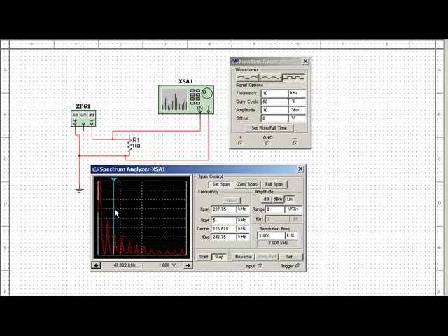And then over a little further, this should be 50, about, yeah, there we are, about 50 kHz would be the fifth. And then here to almost 70, that would be the 7th. 90, that would be the 9th, and then about 110, that would be the 11th, and let's see, what's the next one here, 130, 13th, and so on and so forth. You get the idea here, and this would go on indefinitely.